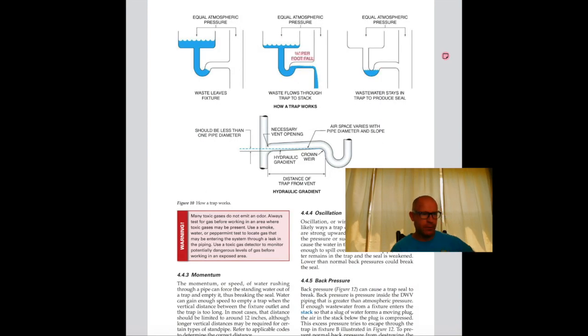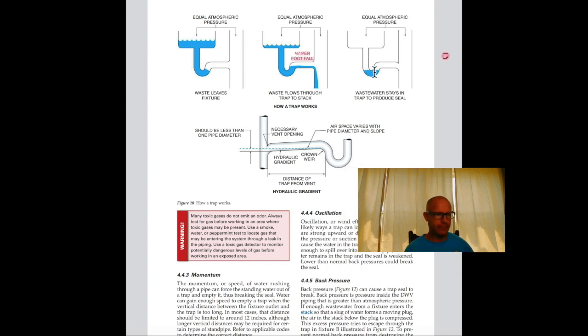Alright, I just spoke about siphonage. Siphonage can happen when you have 2 traps back to back, or if you have an S trap, which is also against all codes. But if this trap arm is over a 1/4 inch per foot fall, you could also have a siphonage here. So what happens is this water drains down into the trap. The pressure here is greater than the pressure here. So what happens is all this weight pushes this water up and out. The idea is here, you want it to push it up and out, and then this water stay in place, because this is your trap seal.